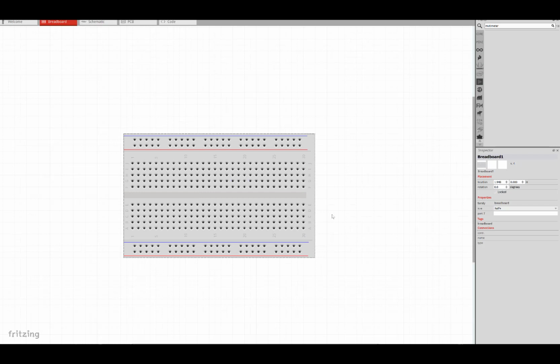Now the breadboard is a very nice platform for making connections. Instead of making connections of the wires and then taping them together, we can insert the wires in the holes in the breadboard. So first thing you need to do is understand how these holes are laid out. You will notice that on the top, if you lay it like this, there's a blue line running, and next to that blue line you have all these holes. Underneath this breadboard, if you were able to open it up, you would see that all of these holes are actually connected together. When I click on any of these holes, you see all the holes in the same row light up with a yellow color, and that's an indication that all of these are connected with one another.